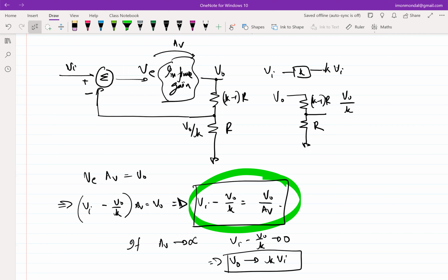This is the concept of op amps with virtual grounds, right? So if you have infinite gain and given that your circuit is stable, the input to that infinite gain block has to go to 0. That's the only possible solution. Okay, that is the analysis part kicking in. But if you have to set up a system to ensure that it works properly using negative feedback, this is the thought process that should play around in your mind.